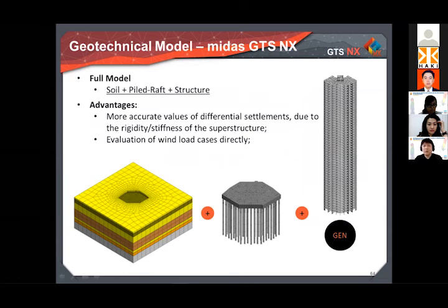So those results differ from the real behavior of the structure, showing higher values of differential settlements. Looking at our model, we created a full model, which is the soil plus the Piled-Raft plus the building structure. And as was said, it is understood that differential settlement behavior seems to be closer than when using other kinds of models.